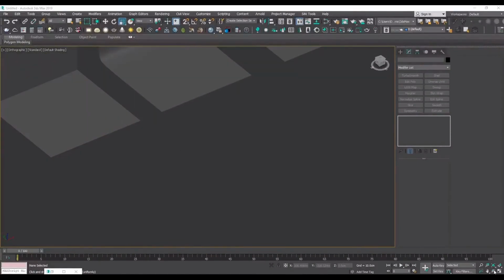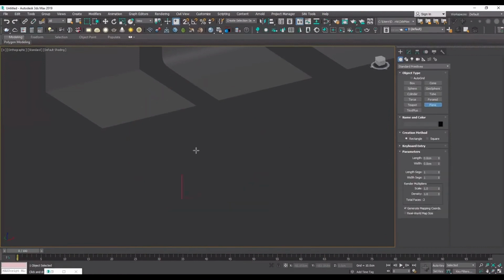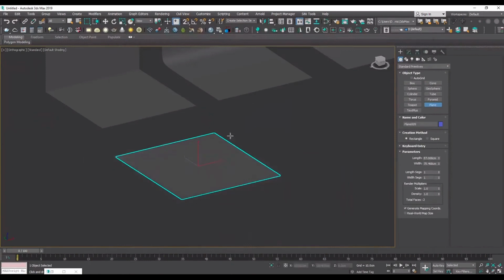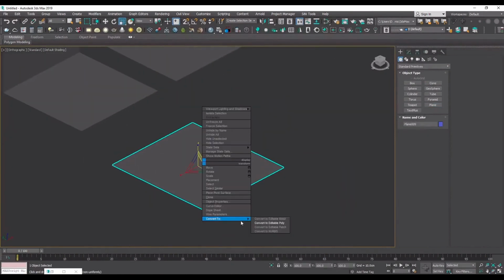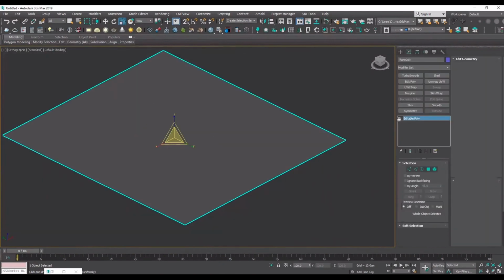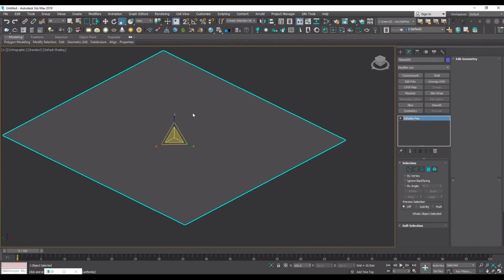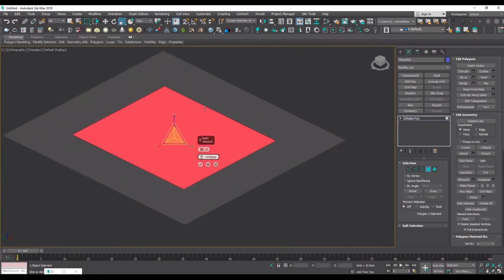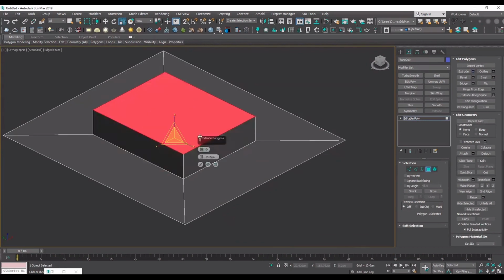Let us continue our examples. I add another plane and assign the material, and this time I'm going to create a hole on our plane as the detail. So the first thing I've got to do is convert my model to editable poly and then get an inner inset from the mesh. After I'm done with that, I will extrude my mesh down.